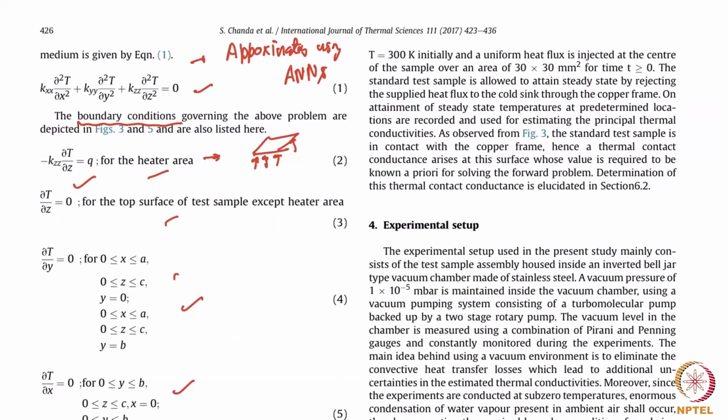You now discretize this, which means you turn it into discrete sets. You have this box, and you put lots and lots of 3D meshes. At all these points, you write a discrete version of the finite difference equation and you solve a linear system of equations. That is going to be a big linear system and it's going to be an expensive solution. Once you solve this, then you approximate it. So you make a table of various solutions.